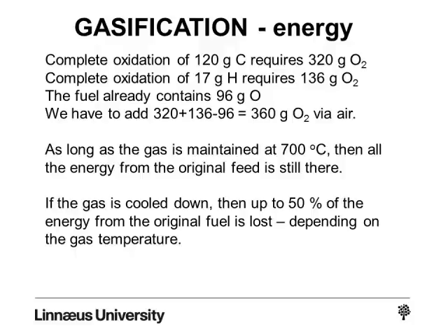So to keep all the energy and keep a good energy balance of the gasification process, we need to retain the gas at the highest possible temperature, unless we want to introduce an expensive and complicated heat recovery process.